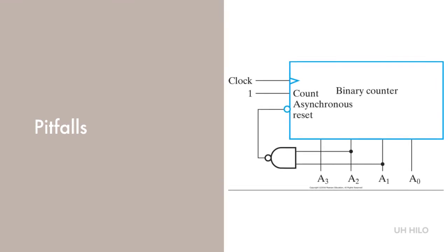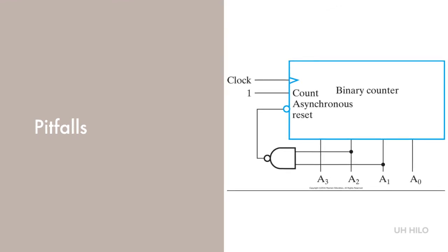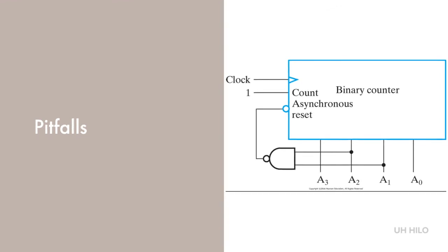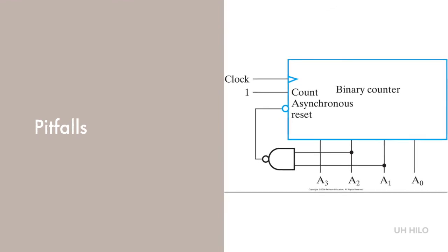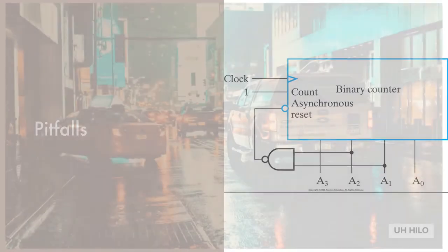Another problem can occur with something known as a suicide counter. Due to the attached NAND gate and its connections, when the count becomes 0, 1, 1, 0, or 6 in response to a positive edge, the NAND produces 0, causing the 4 flip-flops to be cleared, giving 0000. Now, if flip-flop A1 is slow enough and A2 fast enough, the state 0010 could result instead of 0000.